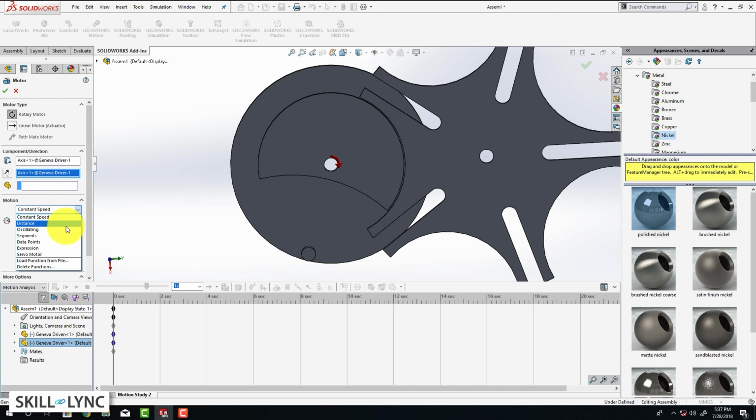As part of your challenge, you will be varying it. Similarly, you can provide distance, and you can type in the degrees by which you want the driver to move, and you can also provide a time for it, right? So you're kind of providing the angular velocity. The nice thing is after 1000 degrees, the driver wheel is going to stop. Okay. Similarly, there is a start time parameter.